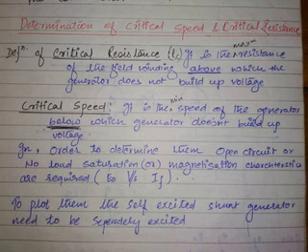The second condition is that the field should be properly connected to the armature. Field and armature should have a proper connection in order to aid the residual flux. The next, third and fourth, we can give to critical resistance and the critical speed of the generator. And the best condition for a shunt generator to build up voltage is to be on no load.